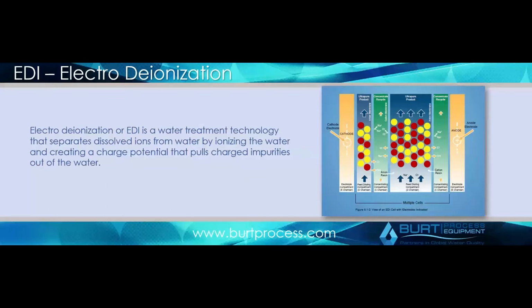We have a question coming in. Is EDI required based on the incoming water quality? No, EDI is not required based on the incoming water quality. EDI is an option to achieve a water quality. EDI cannot be utilized without having gone through an RO. If you have not generated RO water, an EDI system will simply not operate properly. You need to get the ionic content to a certain level to be able to utilize EDI. EDI is an option to either replace the resin bottles or work in conjunction with the resin bottles that can go into a system.